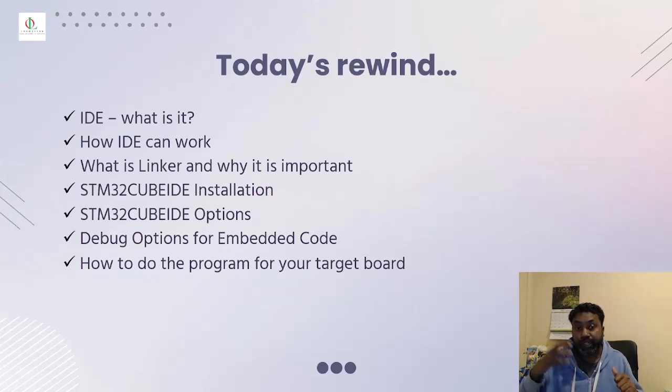We also covered detailed steps about installation of the STM32CubeIDE, what options it has inside, and the debug options available for embedded code, and how to program your target board with all those ISP, IAP, SWD, JTAG, etc.